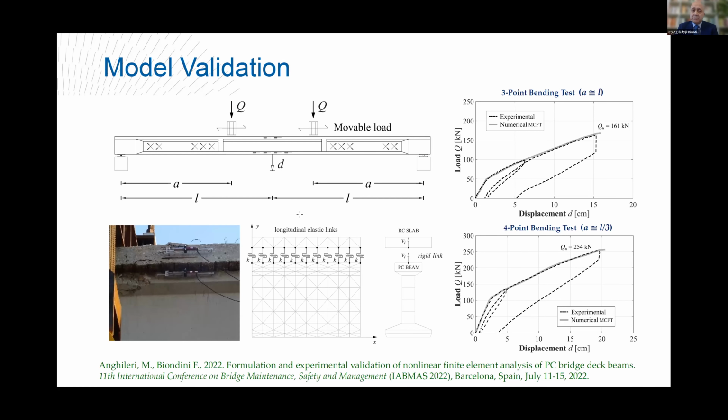A preliminary numerical investigation has been carried out also to compare numerical results with experimental results, and the tested beams have been modeled by taking the construction stages and the effect of a potential lack of the beam to slab connection also into account, because the failure of the beam under load testing was frequently obtained in consequence of the failure of the top slab. And so this has been taken into account also in the modeling of the beams.